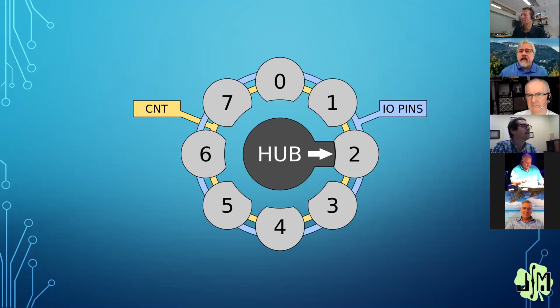They were both set to 80 megahertz. Yes. Okay, so also we're actually not 8 times the bandwidth, we're actually 16, because it took 2 clocks for that thing to rotate positions on P1. And on P2, there are 8 of those spokes, and they click to the next position on each clock. Right. Yeah, you can see it. I mean, the performance difference.